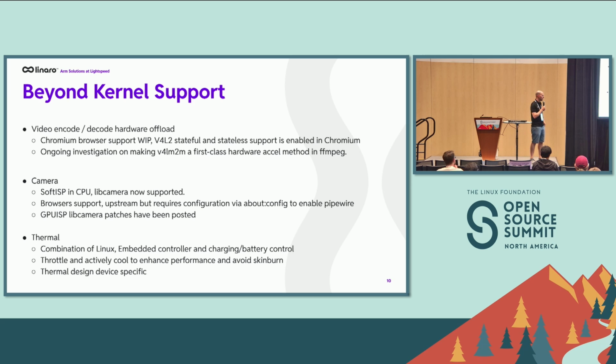On the, for example, the embedded controller, right? That is controlling the fan for the active cooling side. The EC might also know about the temperatures in the system and has its own algorithm at what point to spin up the fan and whatnot. So this would be something that would need to be synchronized between Linux and the EC.